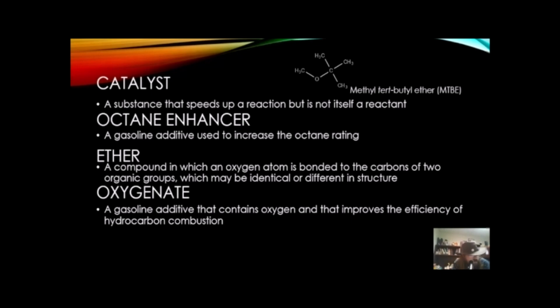Well, the problem is we had something called catalytic poisoning, that these catalysts are sensitive to other things reacting with them and then preventing the catalyst from being useful. Well, the lead from the tetraethyl lead would then absorb onto these catalysts and block them. And if it blocked these catalysts, they couldn't do their job. Two tanks of gasoline and you've just ruined a catalytic converter. If you've ever tried to replace a catalytic converter, that is not cheap. You do not want to be ruining catalytic converters left and right. And so Congress passed another law prohibiting the use of tetraethyl lead.